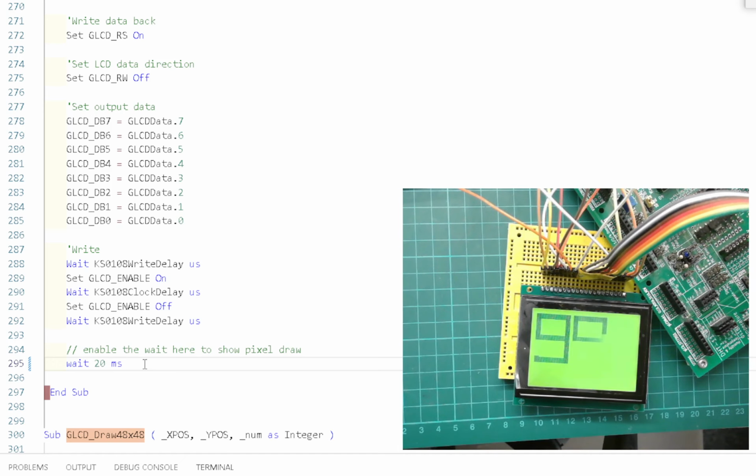And if you watch it very carefully, as it draws those large characters, you can see that the actual overwrite is fully optimized. So it's not actually writing 48 pixels by 48 pixels. It's writing a lot less. And you can see, there we go, that the whole of the 5 to 6 transition was only a handful of bytes, because it automatically calculates that.